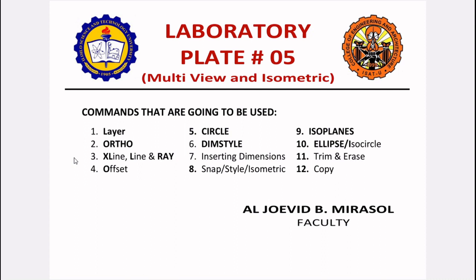DIMSTYLE is used to create dimension styles. We have learned this in plate number 4. We will be inserting dimensions also. With number 8, we will use, this is new, snap, style, and isometric. We'll be changing our drawing to isometric mode.